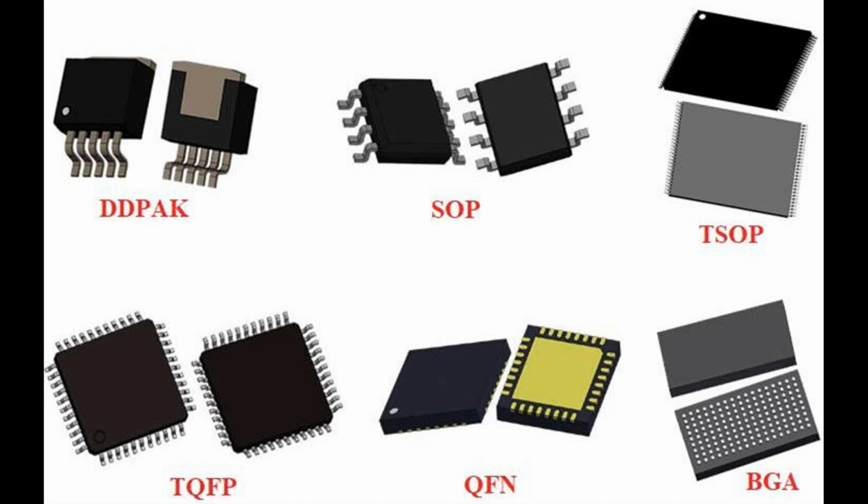2. Serial Peripheral Interface, SPI. Function: SPI is a synchronous serial communication protocol for full duplex communication between a master and multiple peripheral devices. Commonly used for communication between microcontrollers, sensors, and other peripherals. IC type: SPI interfaces are often integrated into microcontrollers, and standalone SPI controller ICs are also available.